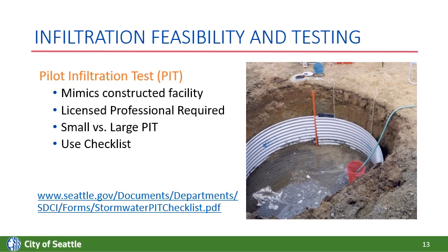So for a pilot infiltration test, again, the pilot infiltration test is required for projects that are infiltrating more than 5,000 square feet on site of impervious surface or 2,000 square feet to a single facility. Again, this needs to be overseen by a licensed engineer. The small pilot infiltration test needs to be stamped and signed by the licensed professional.